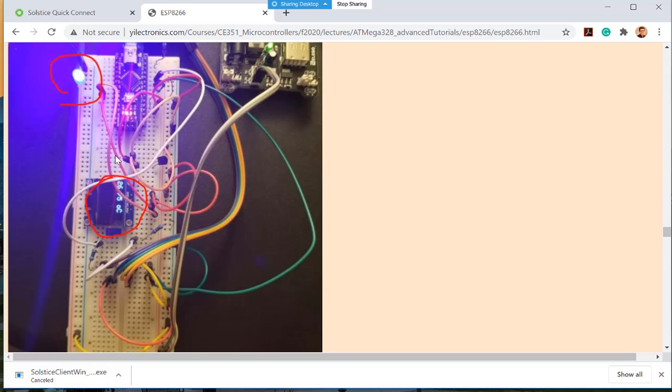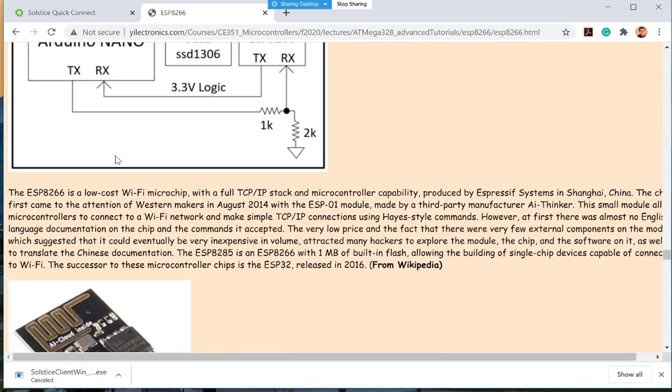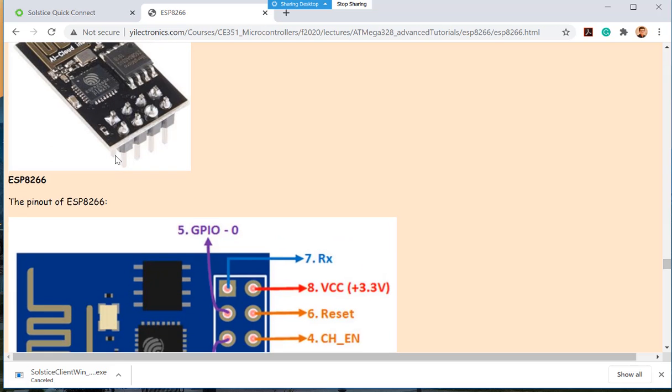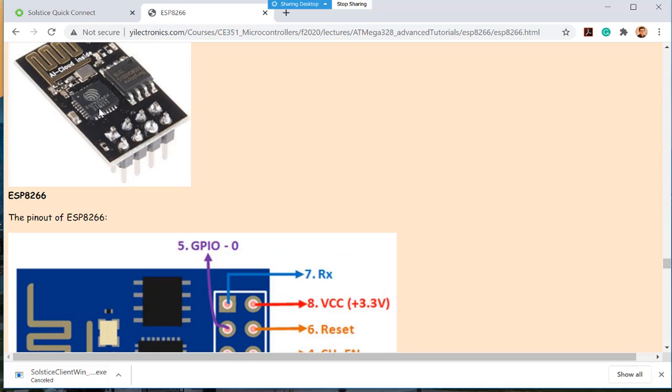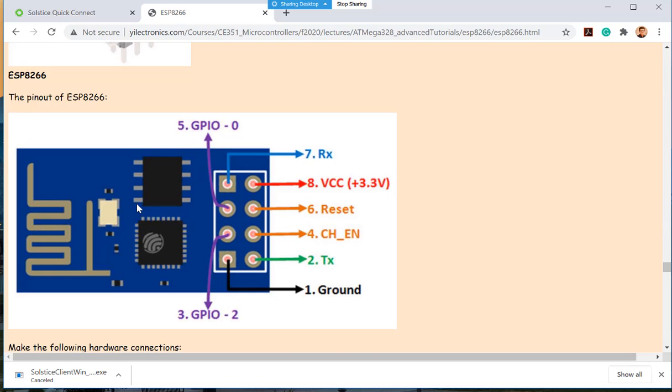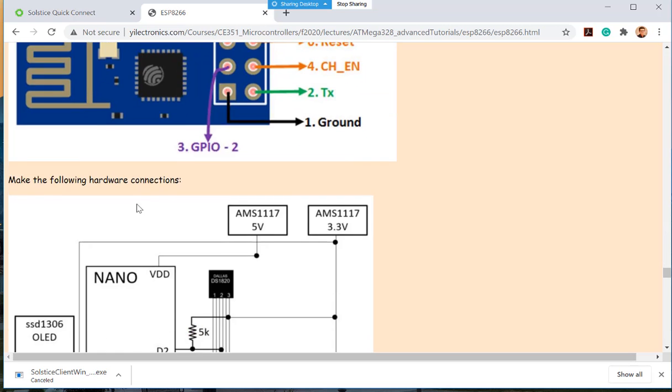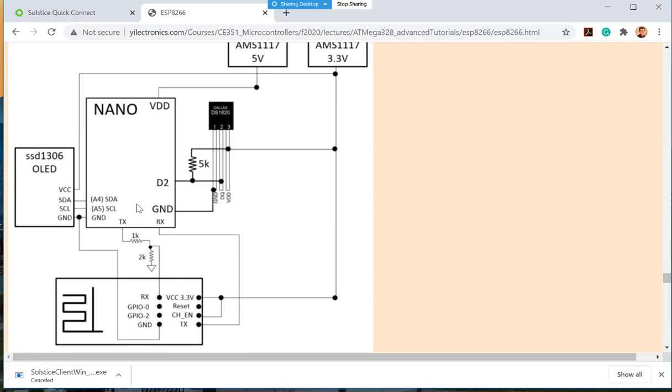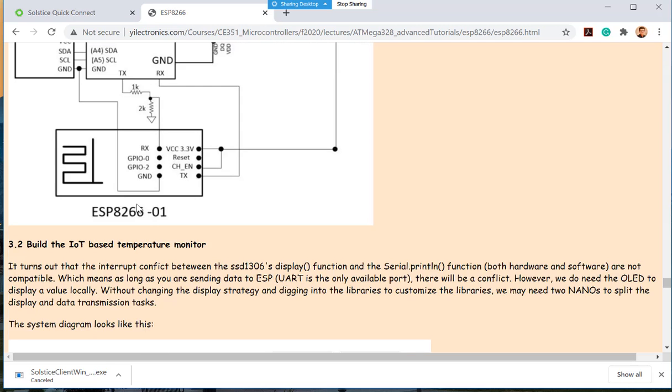Just one step at a time. And then just use another microcontroller to communicate with this Wi-Fi module. If that works, then merge these 2 parts together to see if that works. If you see any problems, you have to disconnect something and debug one part first, and then connect it back. Things like this.